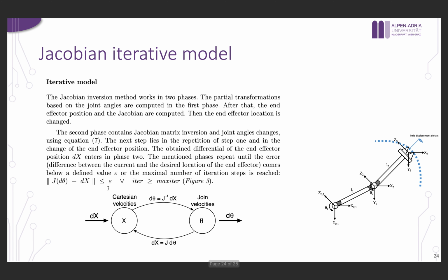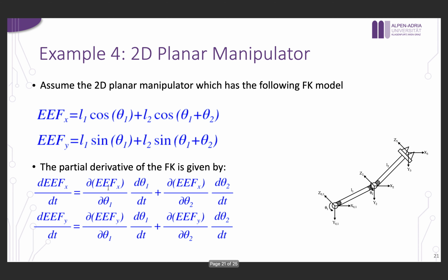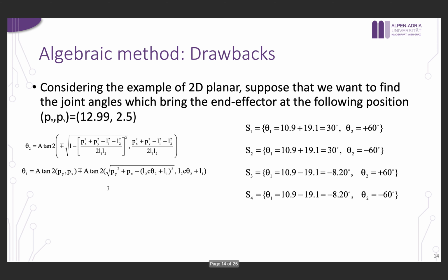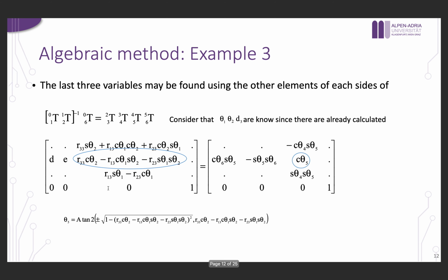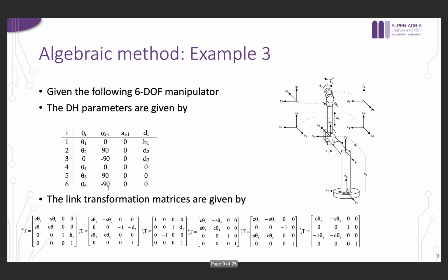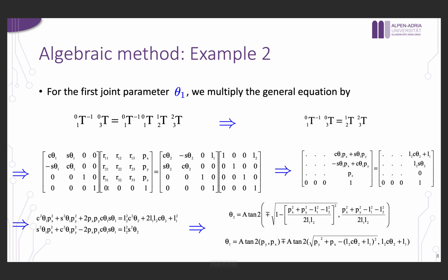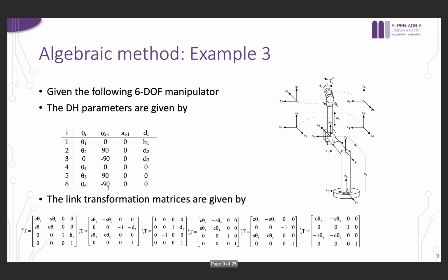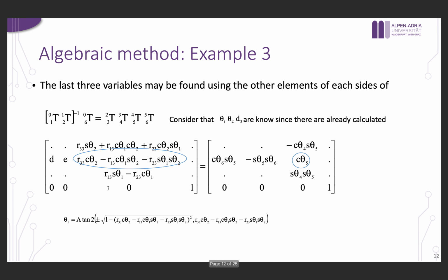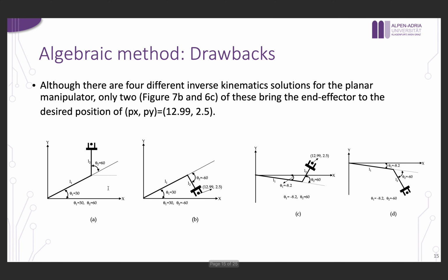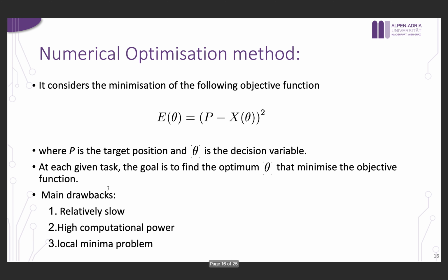iterative method. So in general, we have seen toward inverse kinematics the algebraic method, which is the most common for most robot arms, the industrial robot arms that you buy. You might get the inverse kinematics model with them already. In cases where we have nonlinearity, or path planning or path avoidance, then we could use other methods like numerical optimization methods.